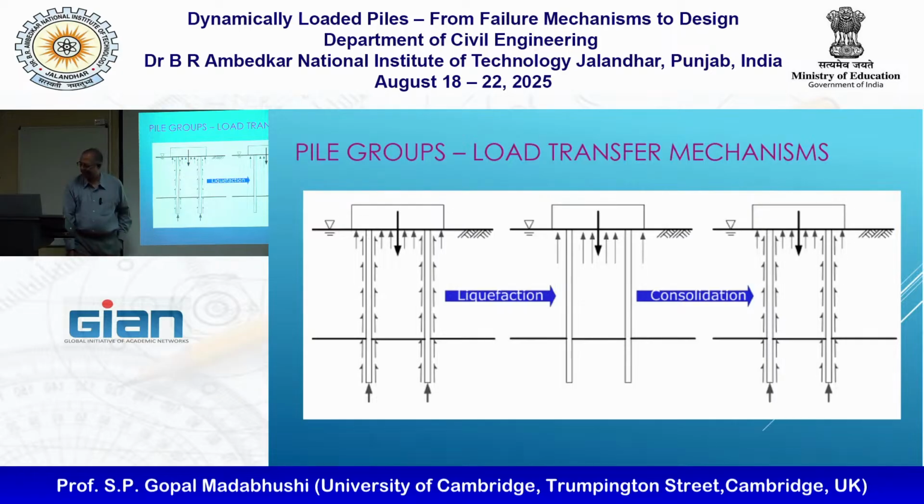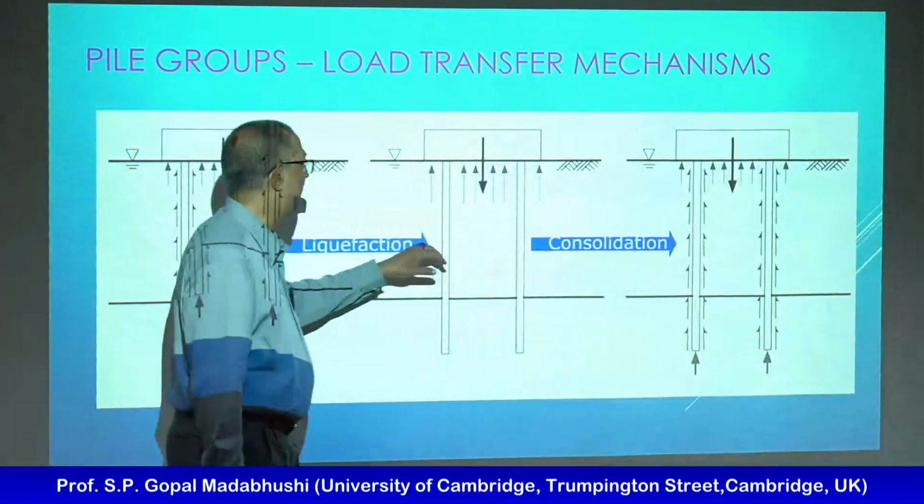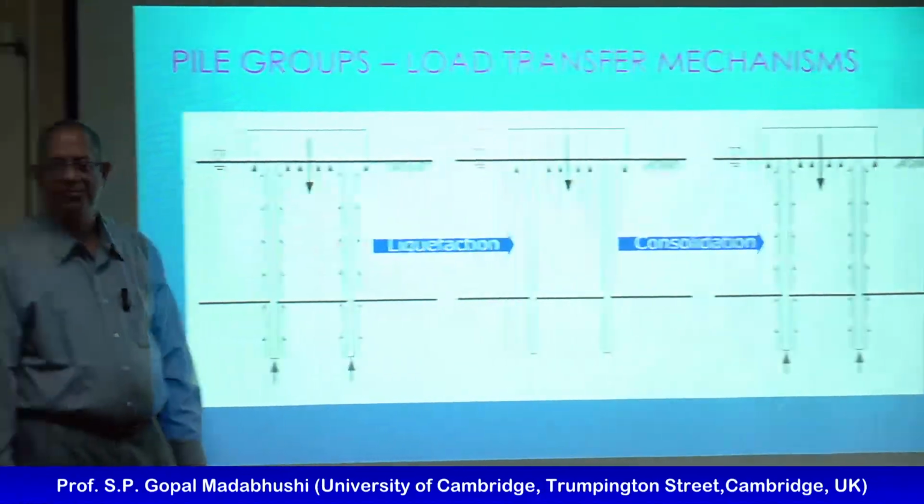So when this PhD work was done, my colleague, the famous Professor Malcolm Bolton, coined this phrase: now you see, now you don't. Initially you see the piles. During liquefaction, piles disappear, and post consolidation they reappear when the pile cap is sitting on the ground.